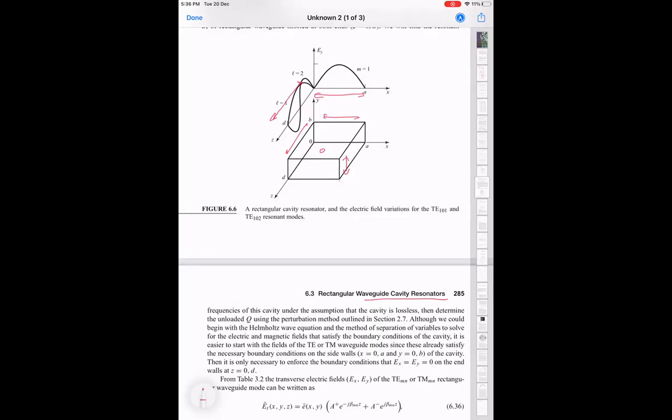Yes. So saying this for a 3D structure, the fact that it's 3D is just a detail. The fact that there is a resonance at that particular frequency, where if you now put some excitation, then with respect to that, it will look like an ideal resonance, which can be modeled by LC. But again, the details of what happens away from the resonant frequency will be different. So this will also be different for a transmission line resonator and a waveguide resonator.